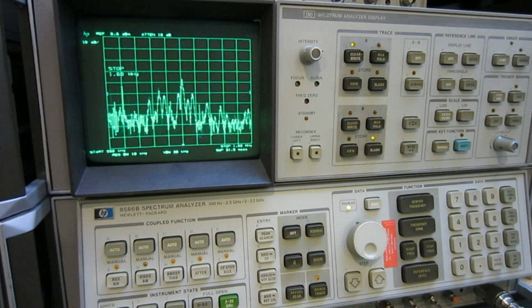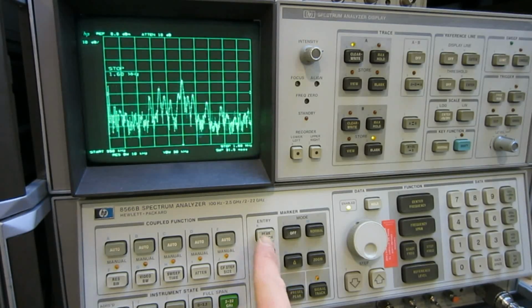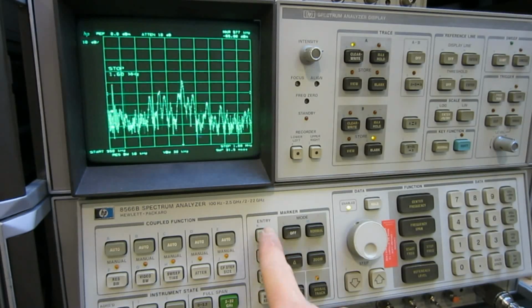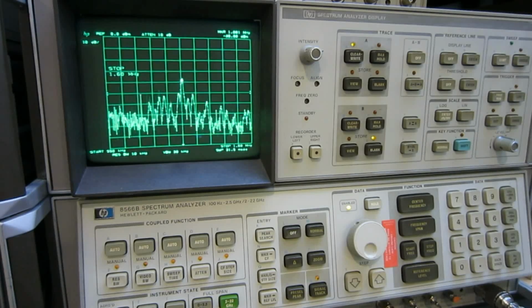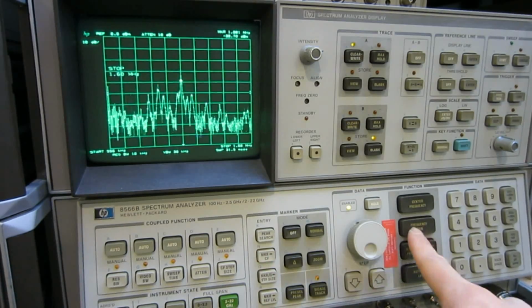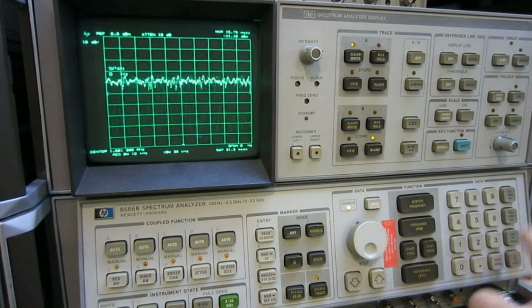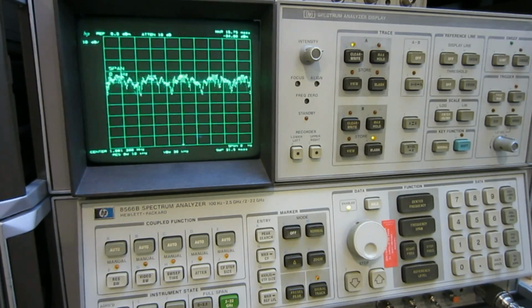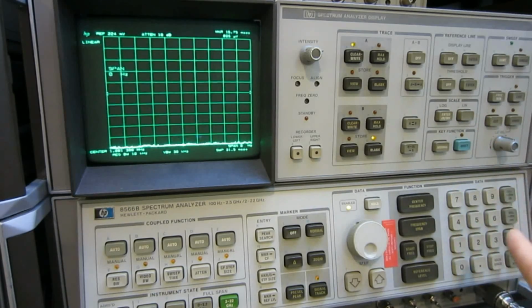And we can see quite a few signals here, and all these are probably just stations. So I'm going to choose the strongest right now for this experiment. So we're going to do peak search, and the center one is good. So I set it to our center and set the frequency span to 0 hertz. So that is our station. Remember, we have to set it back to linear, and we have to set the reference level correctly.